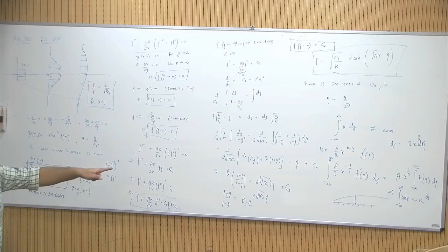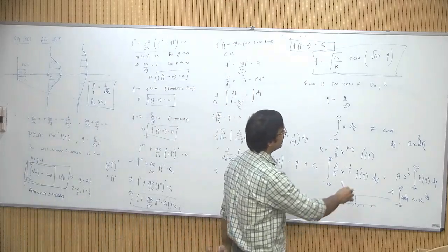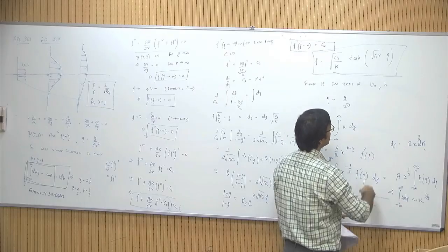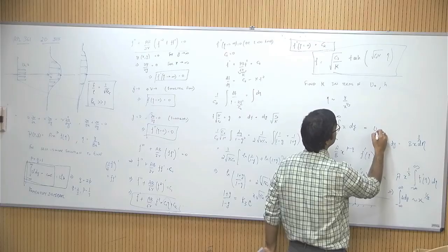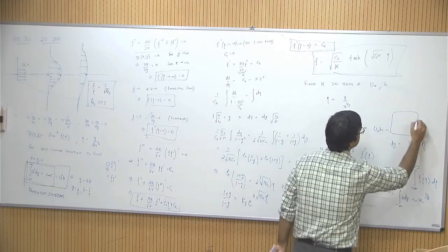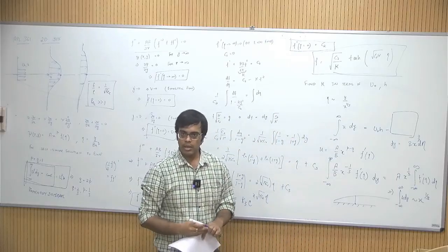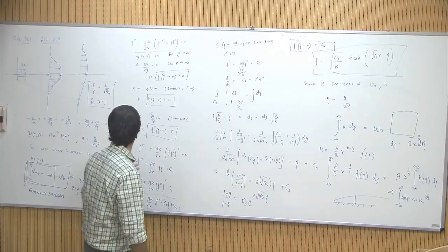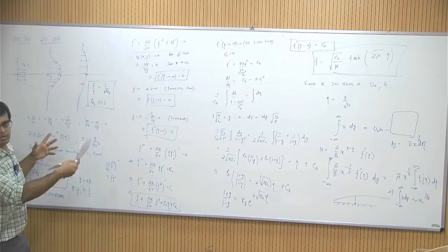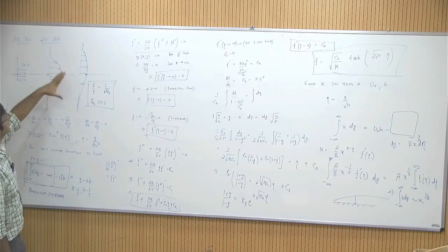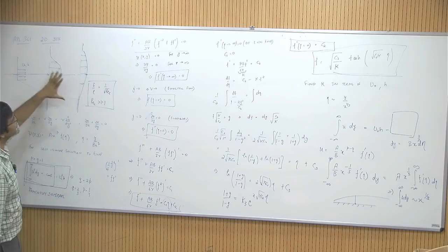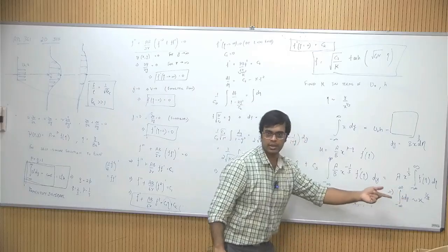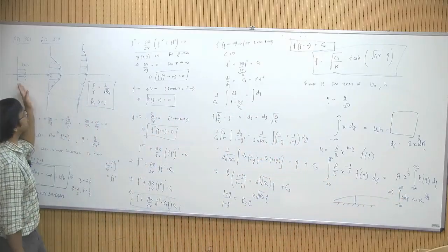Okay, and this brings us to the important point which we outlined before doing all of this derivation, that this quantity was not constant, it was equal to u naught times h minus something. So this minus of something will also be negative, and you can derive that it is a positive influx into the jet, and this fact that your mass flux is increasing in x as you move further downstream.